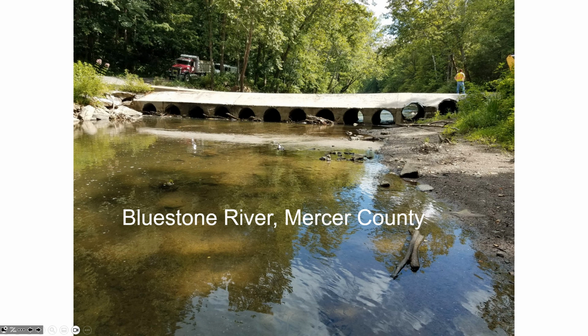And flow over the top of the culvert has a very interesting name. It's called overtopping. If you've got flow going over the top of the culvert, it's easy to remember. But it can be a problem because if water's going over the top of the roadway surface, then it can cause a lot of scour on the roadway, and obviously people can't drive over the road if the culvert is completely submerged and the water is spilling over the road.